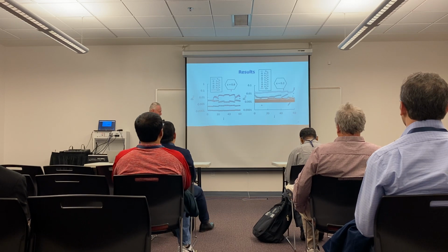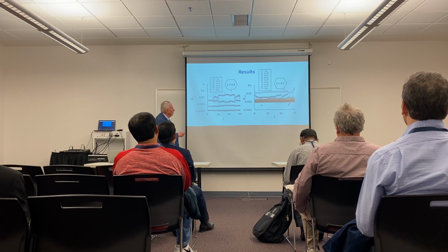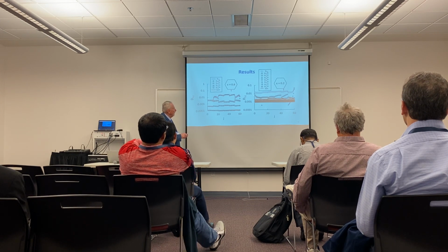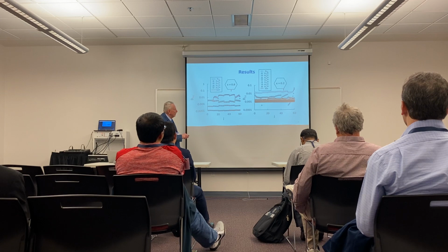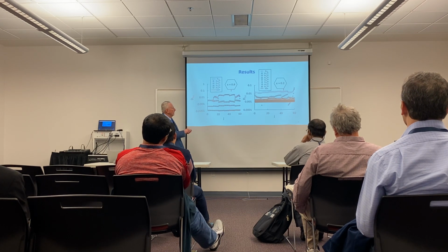If you decrease the emissivity though to 0.1, you would probably anticipate that there's going to be a lot of reflections, and therefore you're going to have to use a lot more terms in your sum. So in this case, I've considered the first 6 orders, and the blue line is the real answer. The red line is the sum of all of these things for each of these surfaces. And you can see there's a noticeable gap there. It's 4 or 5%, something like that.